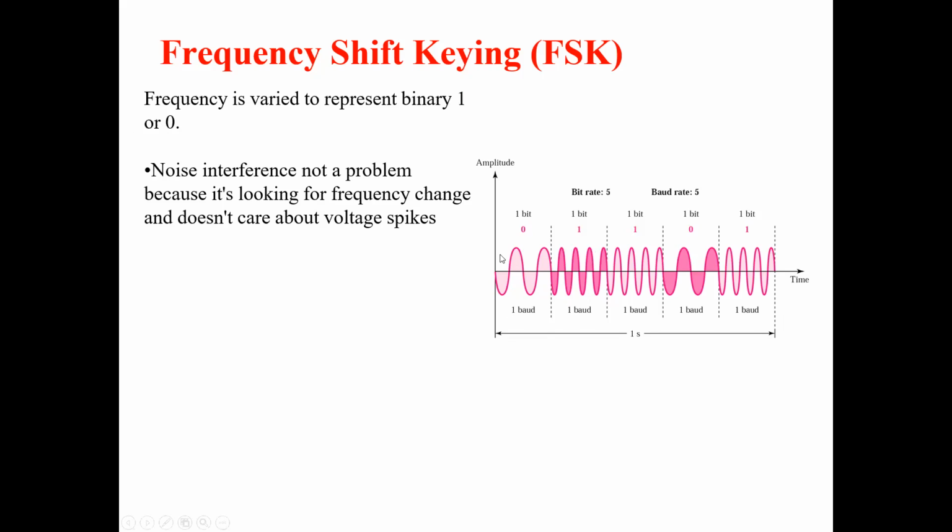We are using two oscillators, one for the higher frequency and the other for the lower frequency. So noise interference is not a problem because it is looking for a frequency change and doesn't care about voltage spikes. So in frequency shift keying, noise is not a problem.